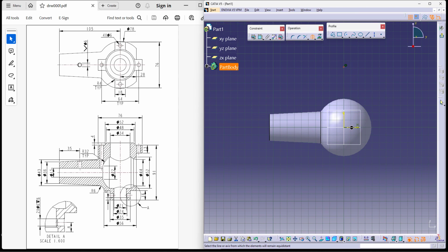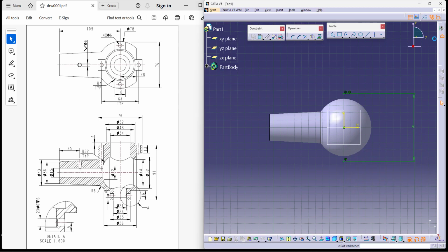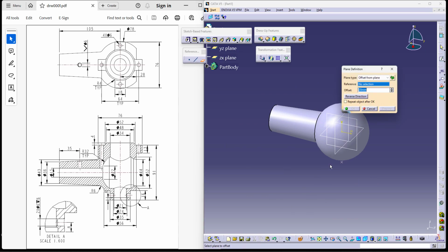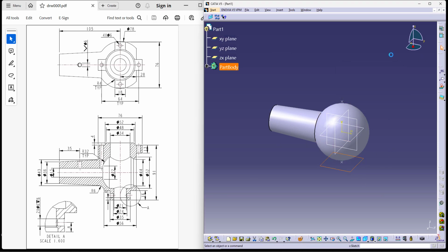So we can use references using our points. We do know that the distance from end to end is 91. So we better take that first. These two are my references. Now I can directly take a plane parallel to the point. This is the reference. It should be parallel with this, and this is the point. On this, I'd like to make the 56 dia sketch.